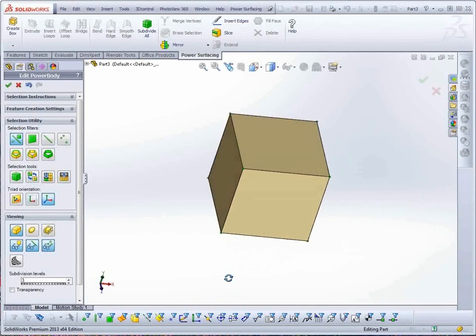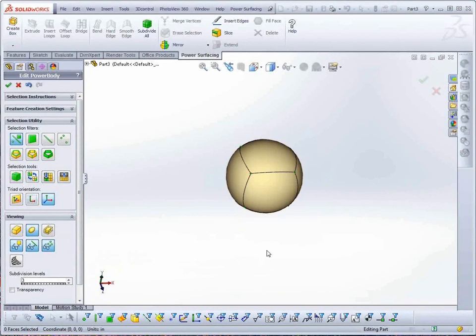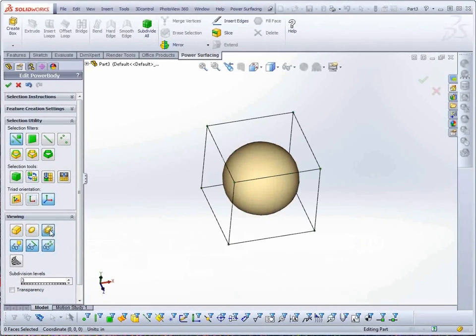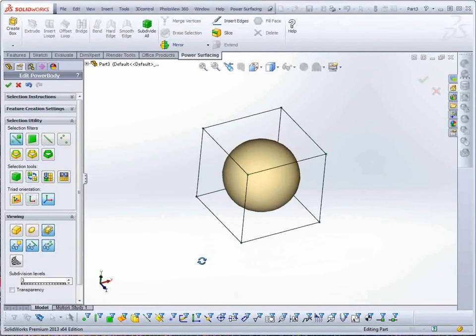With Control, the control mesh shows the base object that is used to create the Sub D model. Sub D stands for subdivision surface. The Sub D display mode shows the subdivided model along with the control mesh's edges and their new locations. The default display, Sub D plus Cage, gives you the best of both while the model is still very simple.